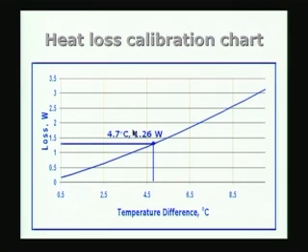and you can see that the loss here is even larger than the uncertainty which we have in the problem. Therefore, it is essential that the loss, which is about 1.26 watt in this particular case, is taken into account, because if you do not do that, you will incur a very large error in the value of k which is determined, even though the k itself has an error of about 6.6% because of the uncertainties in the quantities that are measured.